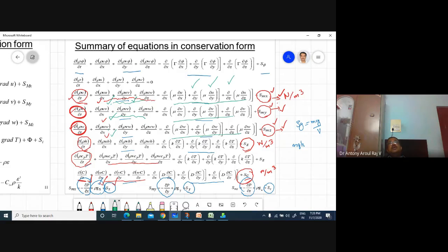In those places only, you'll be having viscous friction, and these terms will be predominant. If you try to solve these equations, in those places you will be getting the viscous friction terms. That will give the major loss, as I told you, and the convection terms will give the minor loss. Now we have understood about the various terms in the equation.